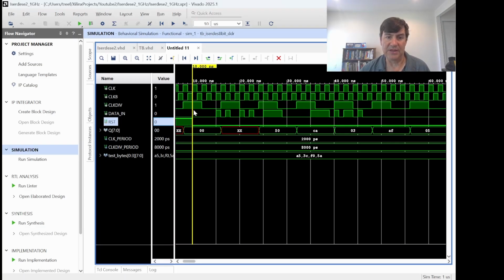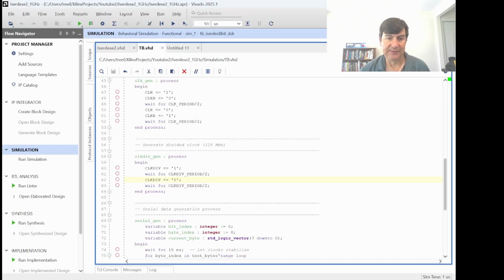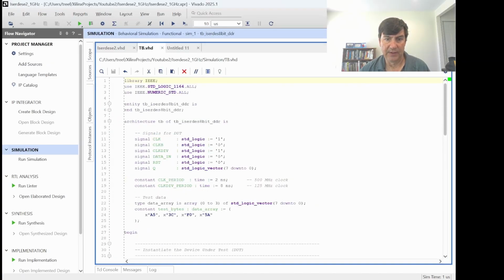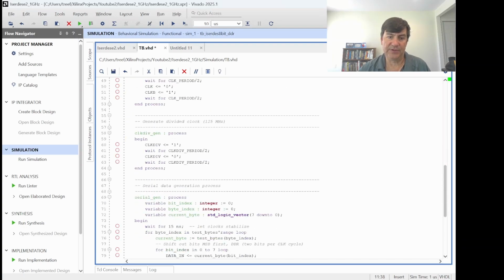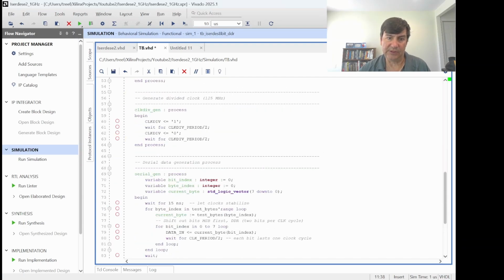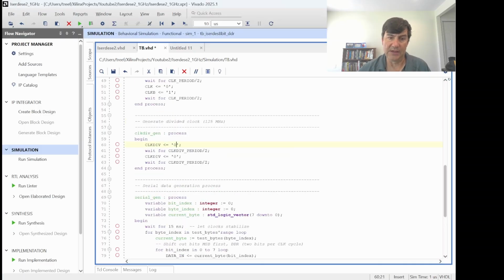You should be coming out of reset in between the falling edge and the rising edge of the clock. So, let me switch it back, and you will see that the collisions go away.